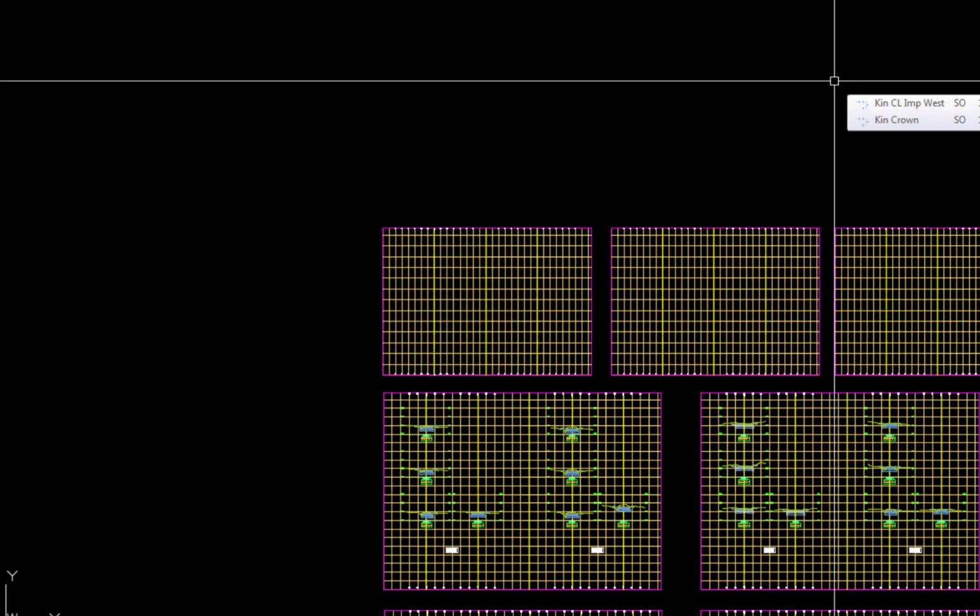When the grid sheets are inserted into the paper space viewport during sheet production, the plotted drawing will have a horizontal scale of 1 inch equals 15 feet and a vertical scale of 1 inch equals 3 feet with horizontal grid lines at a spacing of 1 inch equals 5 feet.